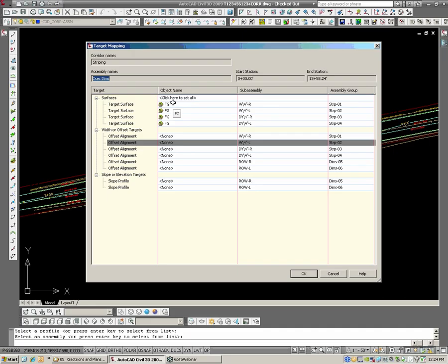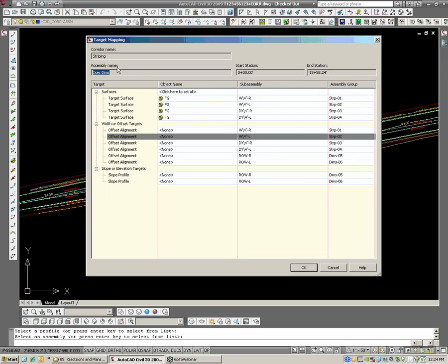It wouldn't actually lock up your computer, but you'd hit OK and you'd just see the little progress bar at the bottom keep scrolling and never stop, because it keeps infinitesimally updating the surface, which is built from the corridor, and the corridor reads the surface, which is built from the corridor, and it just keeps going back and forth. So don't do that. Make its own. If you're doing this striping thing, put it in its own corridor.